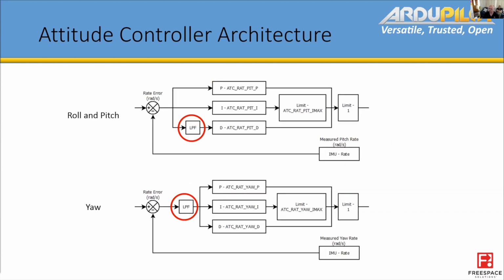So this shows the fundamental difference in the filtering positions of roll and pitch in the error versus the D-term filter. So this is the error coming into our entire PIDs here. And in yaw, we actually place this low pass filter here, and we have a switch effectively that we can turn on or off that moves it to just the D-term or all of the terms.